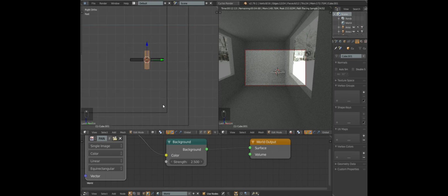Alright, now we're going to improve one last thing, which is how it renders. The little camera icon on the right is the render menu, and there are a few things we can do to help with the rendering. Let's stretch this out so everyone can see it. For the render samples, you could put that up to like 250, so it's going to go over 250 times to try to get the best possible image. Preview is at 32, so you see it's real noisy.